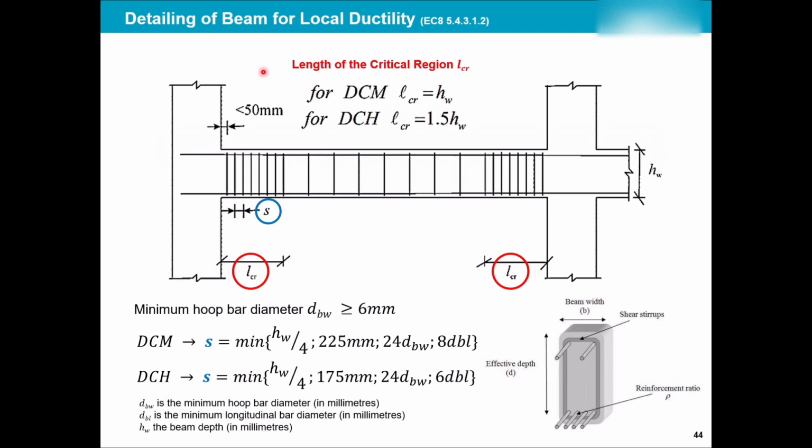So you do not follow the same traditional way that you analyze your building, where you use the same moment and shear diagrams for the beam and for the column. The columns will have a new moment and shear based on the new beam that you have designed, which acts as the weakest link in your capacity design.